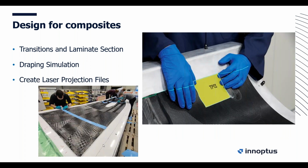They also added a cool functionality that you can export every ply, because that's a layup of different plies, every ply into a file, which can be imported into a laser projection machine, which gives you the placement of the next level. You see here, I want to add a new ply to it, and with the laser, it will give you the position projected on top of your mold where you want to place that.